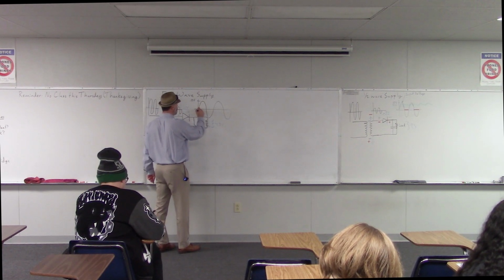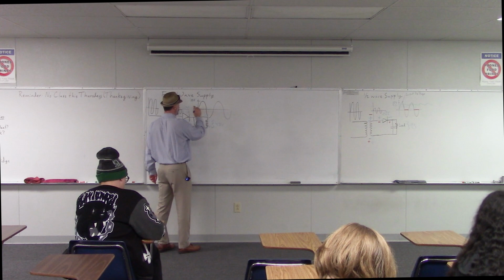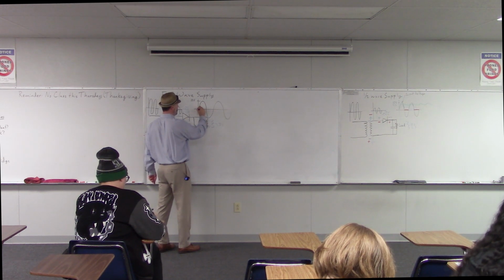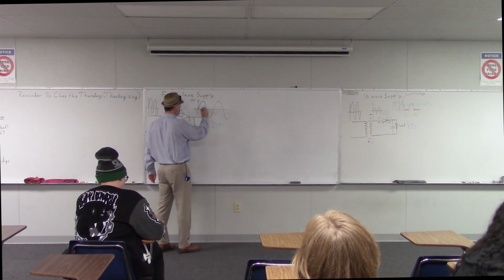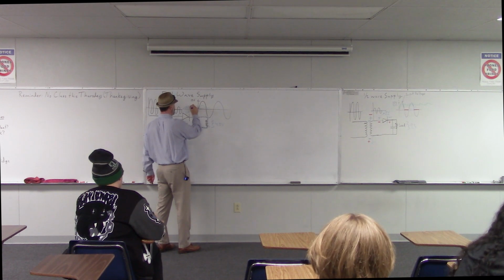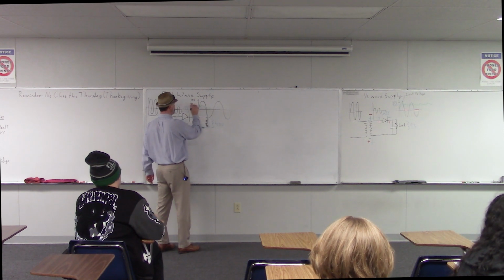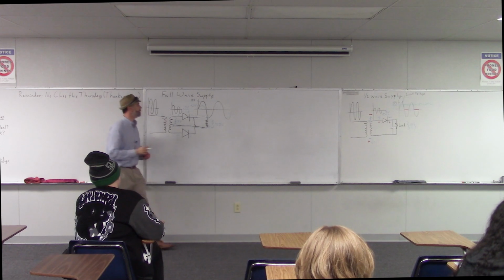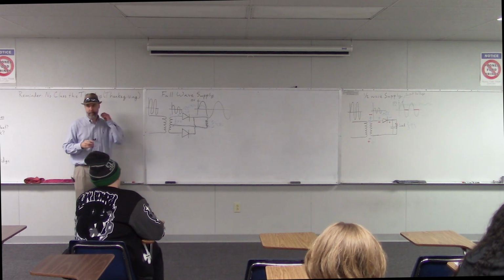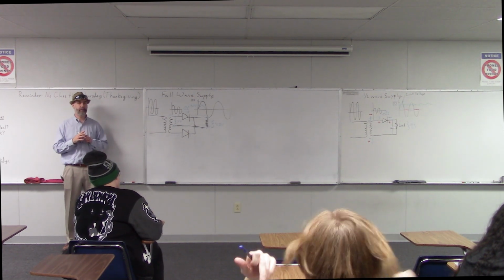So we got 4.3 volts there. So our output here, when the input is positive, the output is positive also, but it only goes up to about 4.3 volts. Okay? Any questions about that?